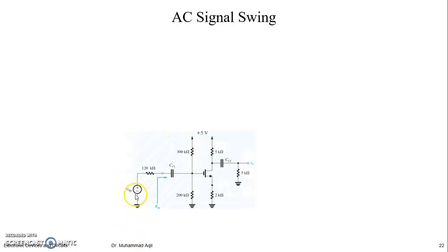Now if we insert a V signal, then this AC signal will be coupled to this circuit, and for the time being it is coupling at the gate, right? So it means part of this signal will be appearing on this resistor and part would be appearing on the input resistance of this stage, while looking into this side where the AC signal is being injected, right?